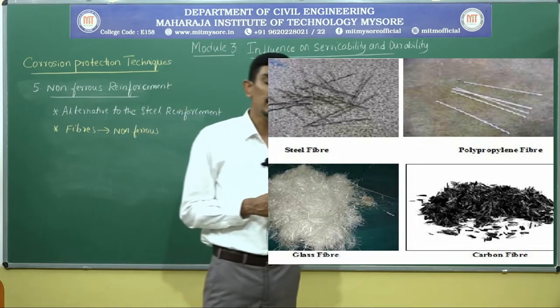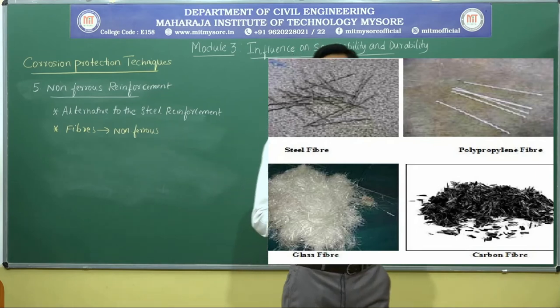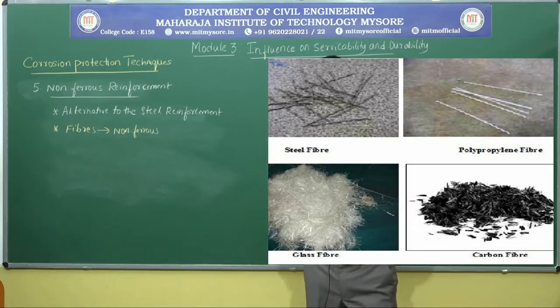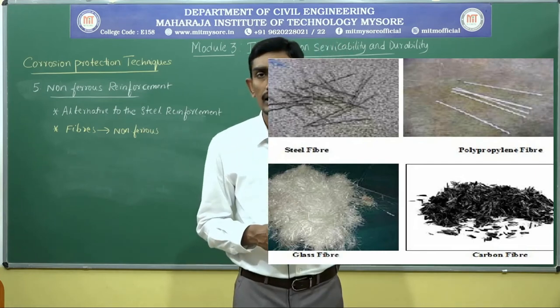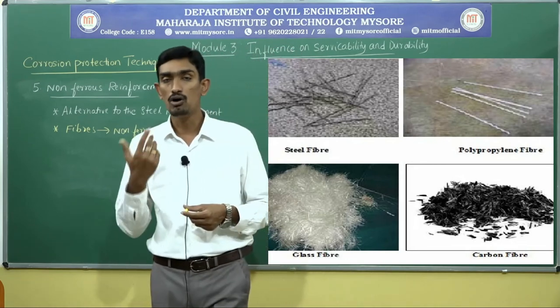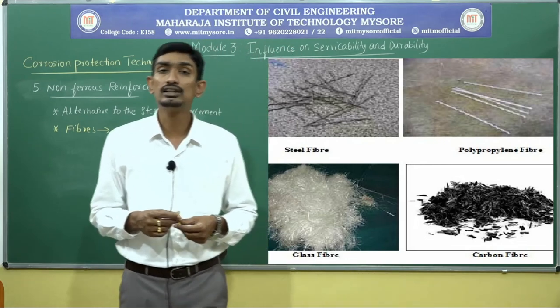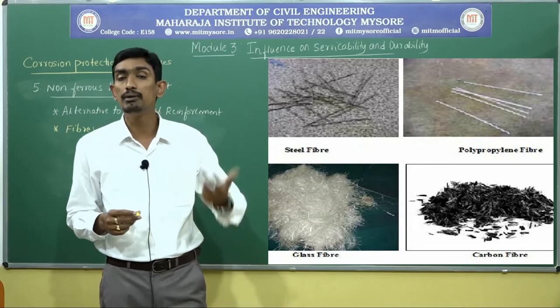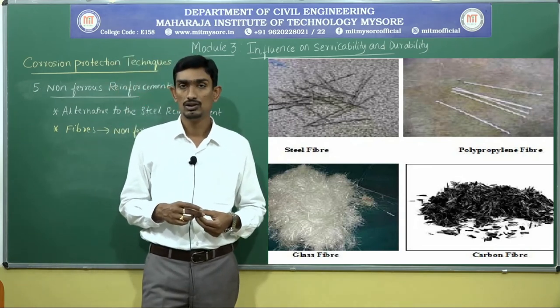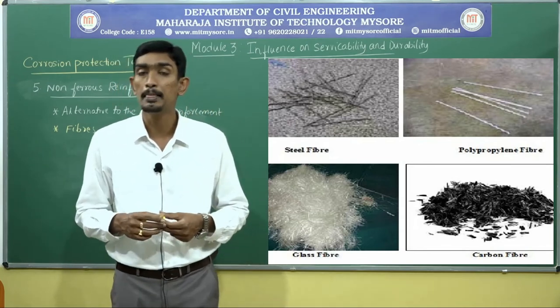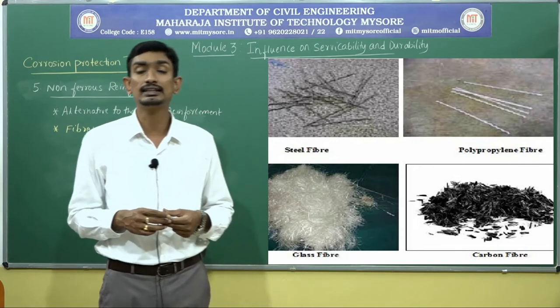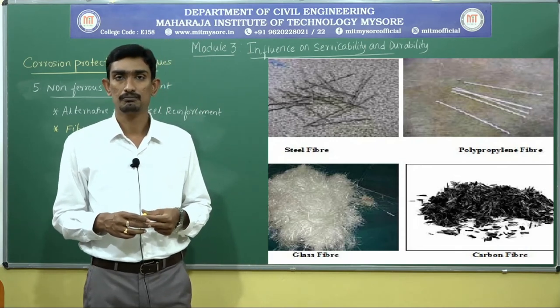And a very interesting thing regarding fibers is that they have a tensile strength and modulus of elasticity more than that of concrete, so that I can embed them inside the concrete. So the fibers will predominantly act as a reinforcing material inside the concrete member.